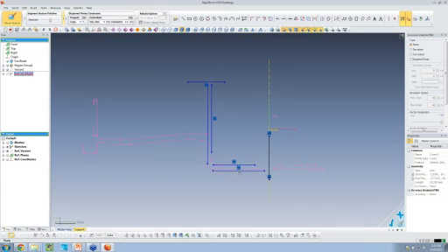So I can also move these around now that they're flat. I can also snap it to maybe the outermost portion of this, or I can take again an average of it. Okay. Now, once we have these drawn in there a little bit, I can start fine-tuning this. Let's do a little bit of trim work, very similar tools to what you may see in your CAD system. And we can go through here real quick and just trim the part up. And I'm going to trim to the center line right here real quick.